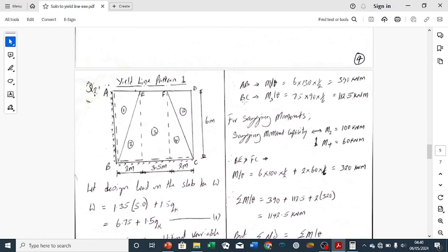We now go for BC. BC is here. Our L in that case is 7.5. That is the length. Our M, remember the moment across BC, was 90. And our theta: this is the place we are calculating, and this is the place of maximum displacement, and that distance is 6. That is why we have our theta here as 1 over 6. And that calculates our hogging moment.